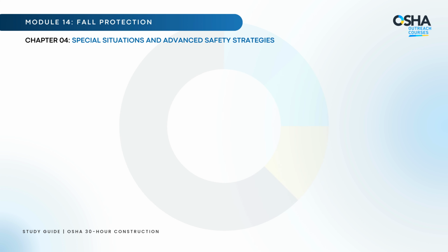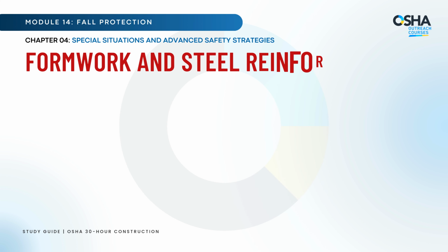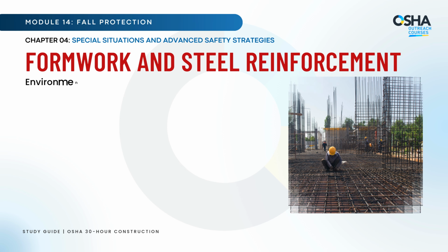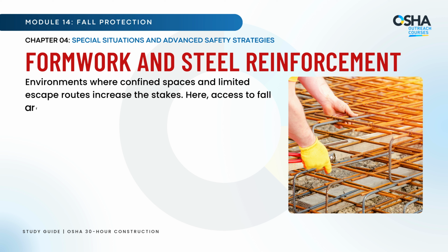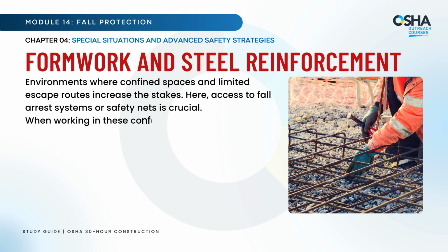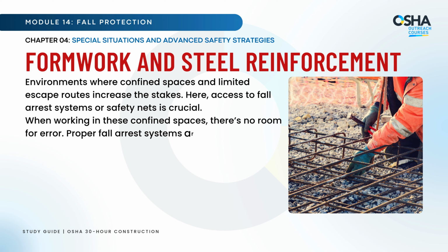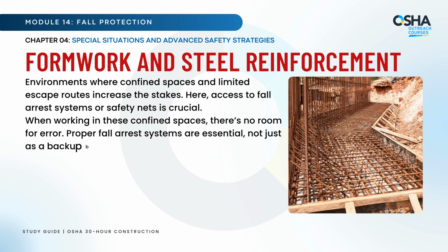Next, let's talk about working around formwork and steel reinforcement. Environments where confined spaces and limited escape routes increase the stakes. Here, access to fall arrest systems or safety nets is crucial. When working in these confined spaces, there's no room for error. Proper fall arrest systems are essential, not just as a backup, but as a primary layer of protection in high-risk settings.